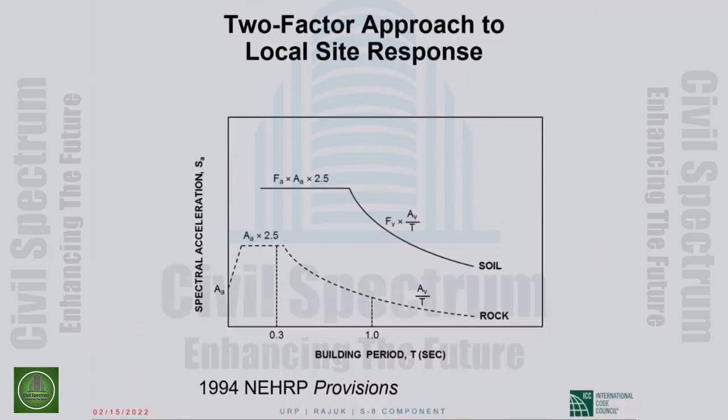and I have talked about this in one of the segments, we became very aware that the short period part of the spectrum, this part of the spectrum, and the long period part of the spectrum are amplified differently by soft soil overlying rock. Okay, so short period ground motion is amplified differently by overlying soft soils than is long period ground motion.